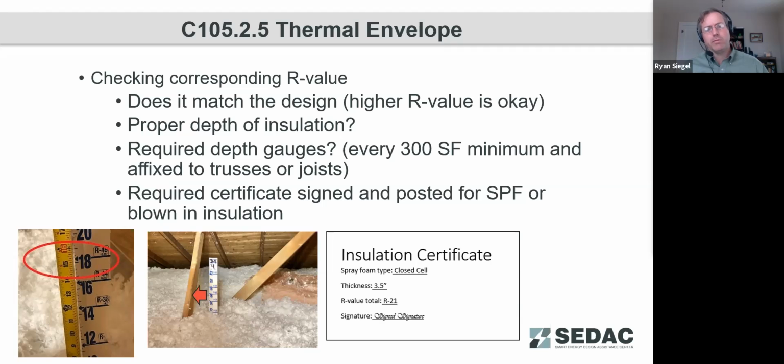One thing that we are depicting here, if you do have this, is making sure that the markers and gauges were installed correctly. Here we show where a depth gauge is showing that insulation at a particular depth would be 18 inches, but using a tape measure, it was found that that would actually only be 15 inches. So this gauge is actually slouched by almost three whole inches, which could dramatically change the performance of the building and the comfort of the occupants therein.